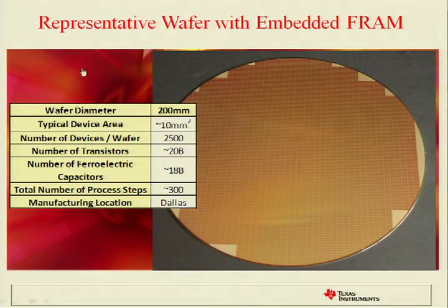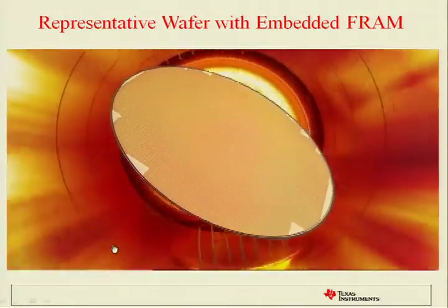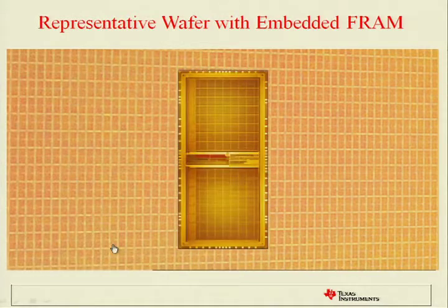So now, if we click on this, there's a little bit of a 3D movie here. And the wafer rotates around a little bit. And then we're going to zoom in and look at a specific die. And we're going to go ahead and expand that die so I can talk about what happens a little more at the micro level. So in this case, we have a die that's around 10 millimeters squared. And at the outside of this die, you see these silverish pads. They're actually aluminum bond pads that are about 60 microns by 60 microns wide. Each of these, what we do is we attach a wire to each of these bond pads and bring them out to another part of this ubiquitous black plastic package that you see with all the electronics. This die itself, there's a memory bank up here and a memory bank down here.